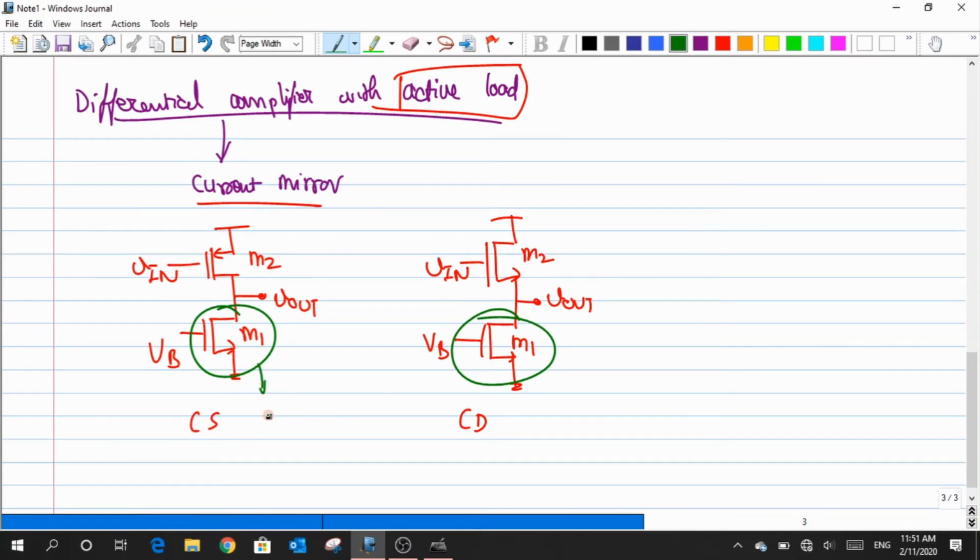Now in each of these cases, we know that this M1 is actually mimicking what is known as a current sinking circuit, right? Both these M1s are basically mimicking a kind of current source or current sinking circuit in this particular configuration. Now, the whole point is that when a particular device or a MOS is being operated in a saturation regime, then I can ensure that this could be replaced with some sort of current sinking or current sourcing circuit.